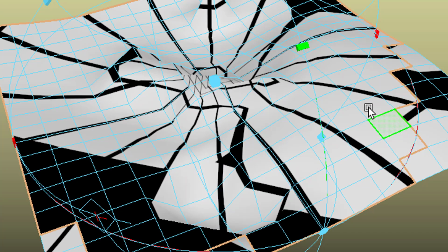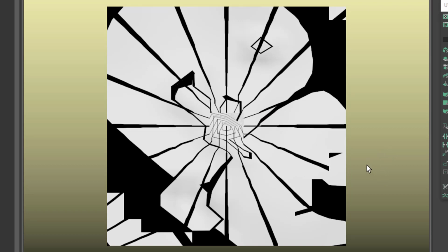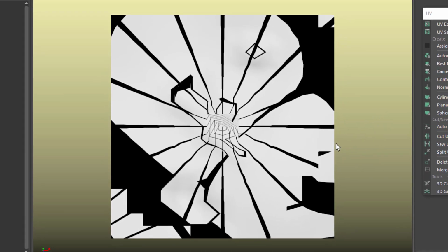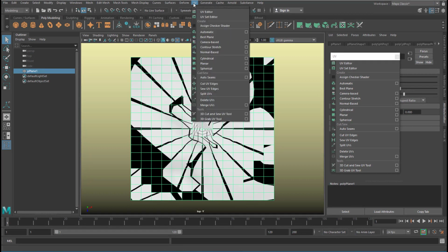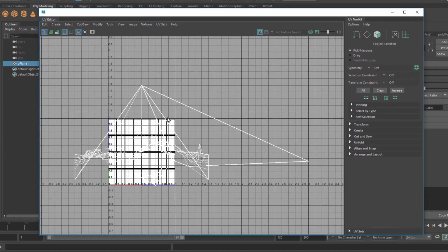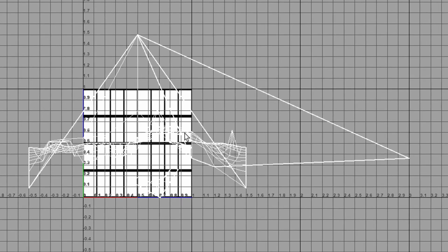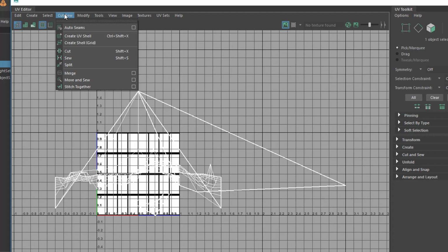Flat image, which is the grid in this case, doesn't look flat anymore. From the top it looks like this now, which can be considered art, but for realistic illustration of a building, for example, this is the wall of the building, it doesn't look okay, of course. So I'm not an expert in UV mapping, but what you need to do is go to UV and UV editor, and the UV editor basically shows you this is our grid, this is the intact grid we planted on the surface, and this is the way we project the surface in the current projection method. Sounds complicated, is complicated.